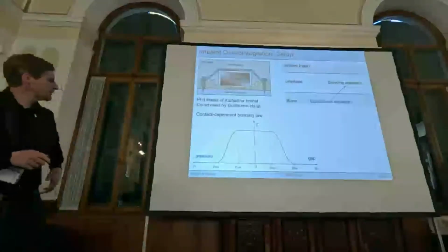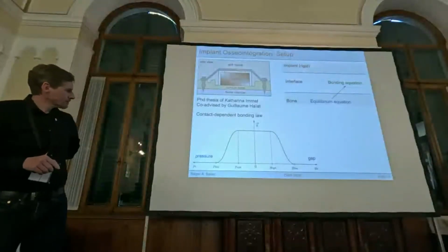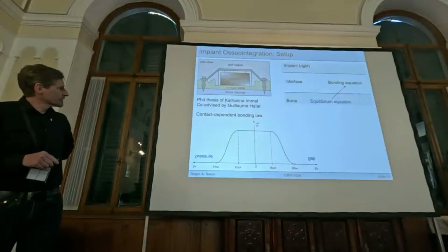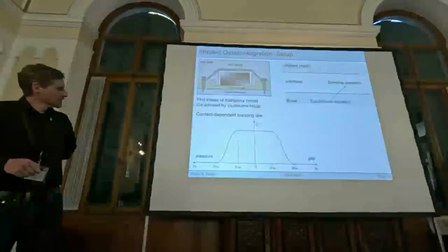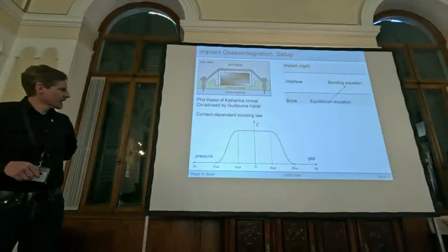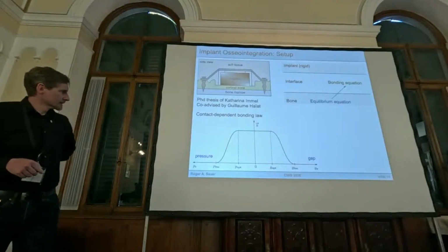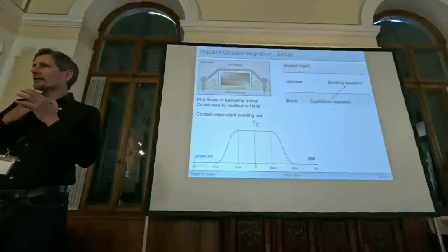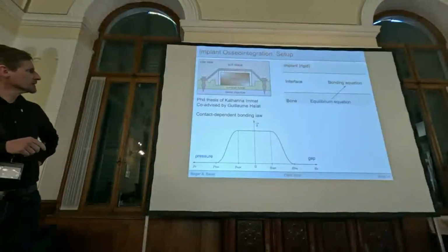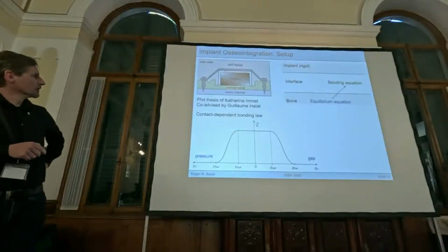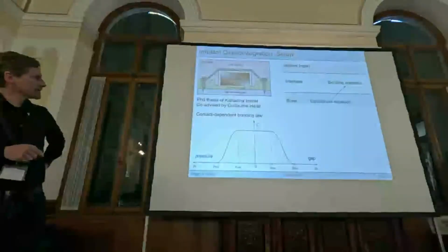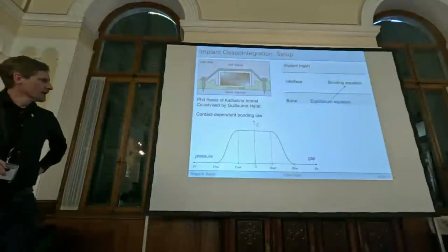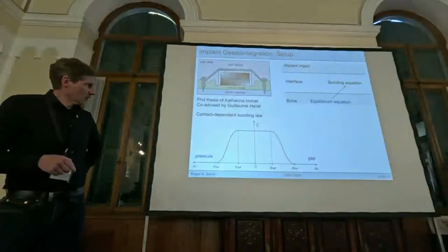The way we have looked at this is to simply investigate a contact-dependent bonding law, where the bonding would be optimal in a certain pressure and gap range, and then beyond that range it would decrease and eventually not bond anymore. That is physical, because if there's too much pressure, it's known that the bond will not form; the bond would rather be damaged. Likewise, if there's too much opening, the bond is also not forming.